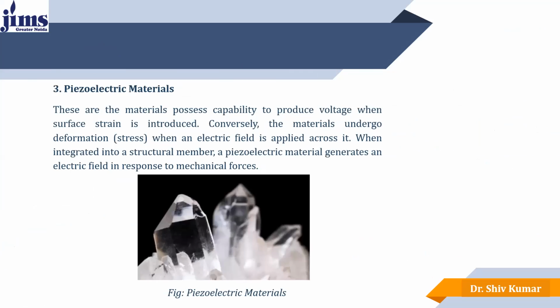Now, the third one is the piezoelectric materials. As the name suggests, electric, it means there may be some change. These piezoelectric materials possess the capability to produce voltage when surface strain is introduced. Conversely, the materials undergo deformation or stress when an electric field is applied across them. So when integrated into a structural member, a piezoelectric material generates an electric field in response to mechanical forces.